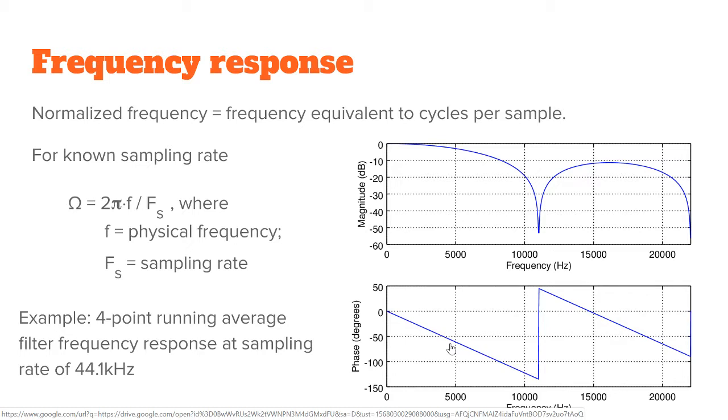And the same way as you wouldn't draw negative frequencies for analog systems, since they are for the amplitude response of any filter, same thing here. The negative side is just a mirror image of the positive frequency side on the amplitude response.